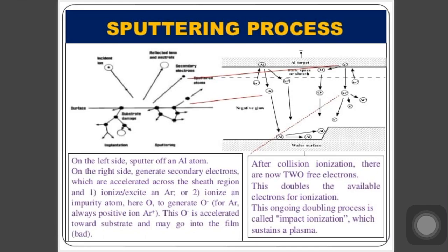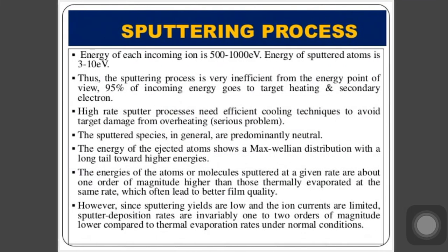Suppose you have to remove certain kind of atoms from the top of the surface, and you have to install some kind of very hard atoms which increase the hardness of your product material. So you are using that kind of coat materials, and we use plasma streams, and due to that plasma stream this coating material's atoms are ionized, and we are focusing towards the product materials, and it will be creating some kind of relevant properties on the required materials. So these are the process.